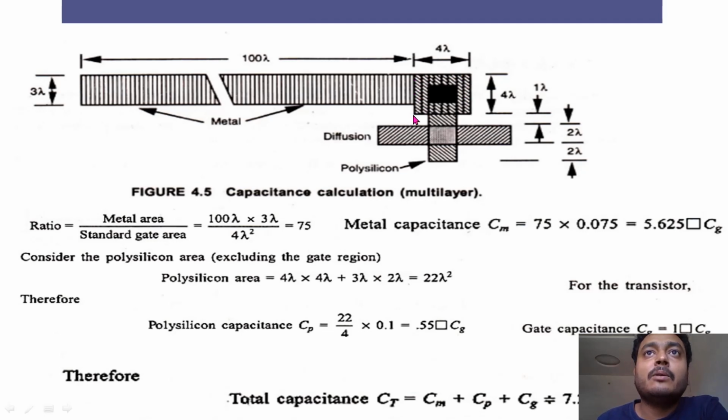One will be metal, on the first floor, and similarly on the ground floor, something like a 4x4 polysilicon will be there. That 4x4 polysilicon will be extended here in this fashion. If you have seen my previous videos, you would easily understand why I'm taking this. You can go back to the video where I took the microwind example using that tool.